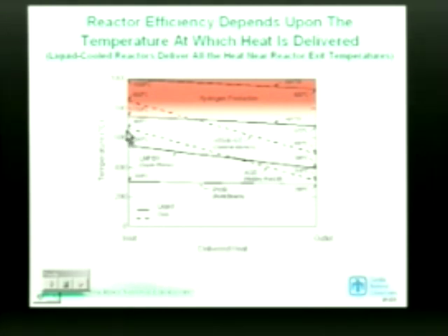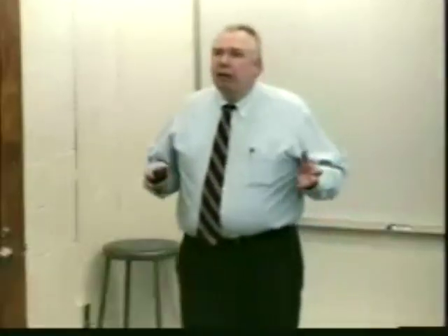For example, if we take a look at the British advanced gas-cooled reactor, about 15 of which are in Europe and use carbon dioxide cooling, such as Hinkley Point B, we find that the exit temperature of the reactor is 665 degrees C, and the inlet temperature to the reactor is 310 degrees C. There's a big temperature drop, over 300 degrees Celsius. If we look at the proposed high-temperature gas-cooled reactor, the exit temperature is 850 degrees, and the entrance temperature is 491 degrees. A 360-degree temperature drop.